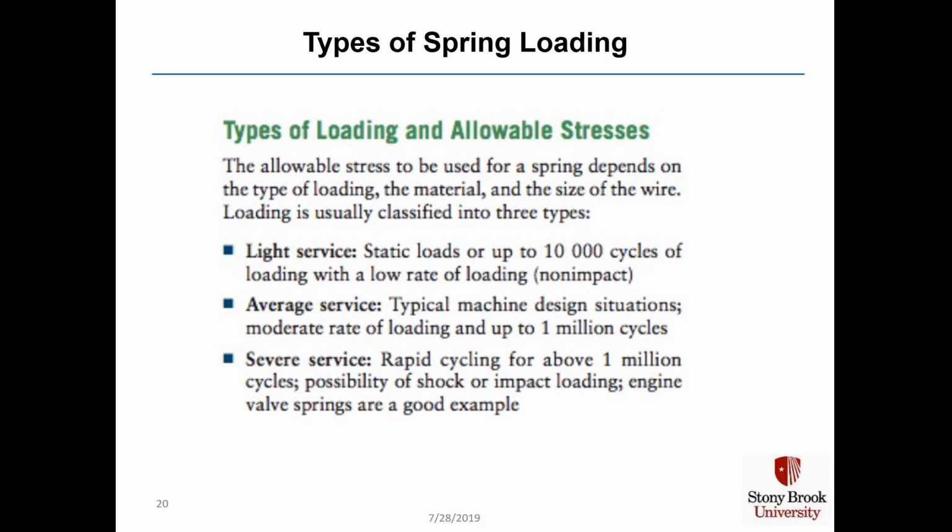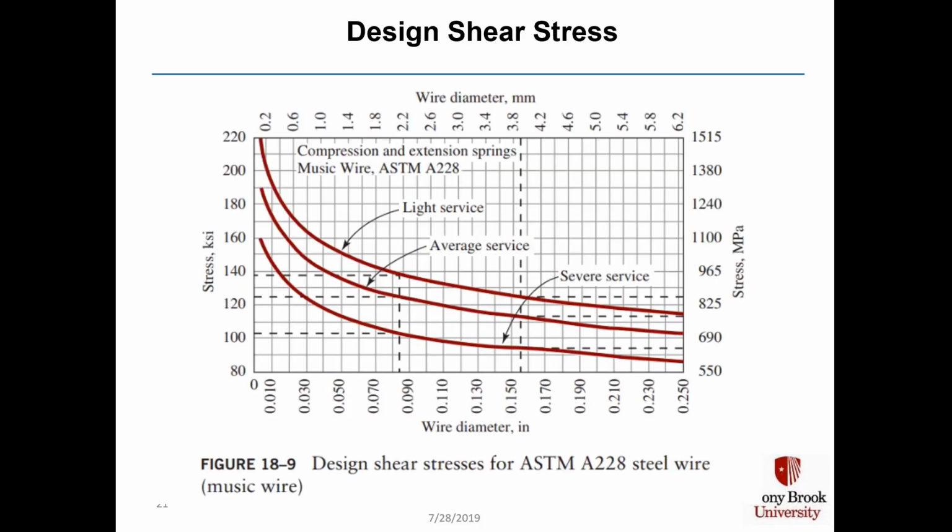Severe service is for rapid cycling above 1,000,000 cycles, possibly shock or impact loading, and typical of engine valve springs. Figure 18-9 shows the design shear stresses for ASTM A228 steel wire, known as music wire.